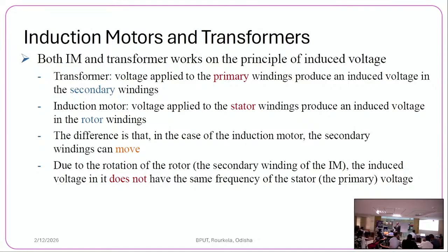Because the mechanical speed of the rotor is now more than the synchronous speed, slip is negative, and it will act as a generator. Slip is negative, so relative speed is in the opposite direction. The relative speed direction reverses because the rotor is rotating at a higher speed, so the induced EMF and current change direction.